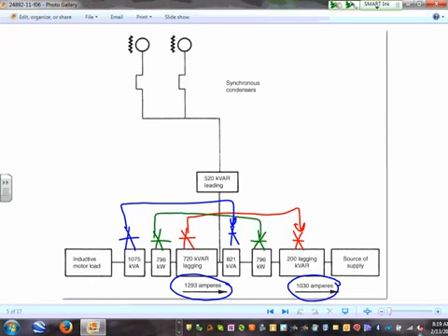I cannot emphasize the concept enough. Why did they get reduced? Because of this value right in here. And because of this, the current got reduced from 1293 all the way to 1030. That's what you guys are doing. You're adding capacitors to reduce the line current.